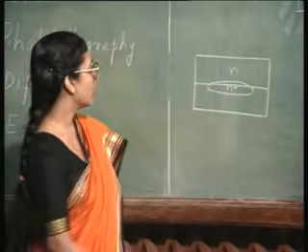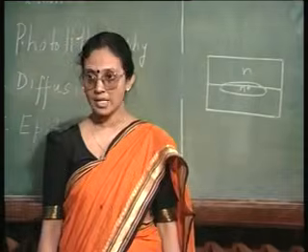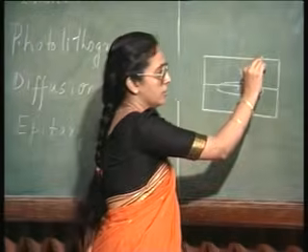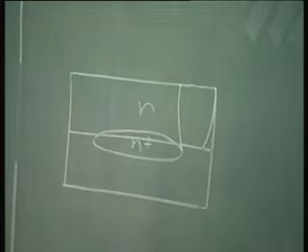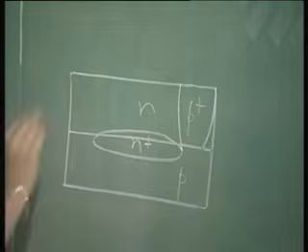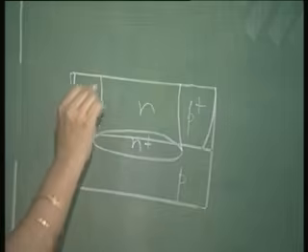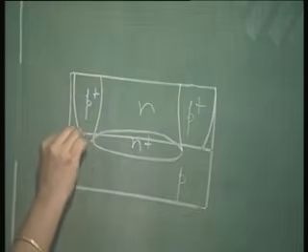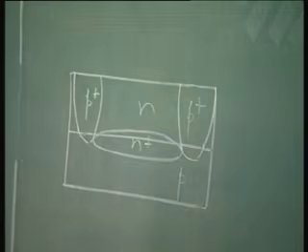What you have to do is protect the active region by means of an oxide and dope here all the way down to the p type substrate by a p plus diffusion. It is very important that this doping comes all the way to the p type substrate. Then you see your transistors are isolated from each other.